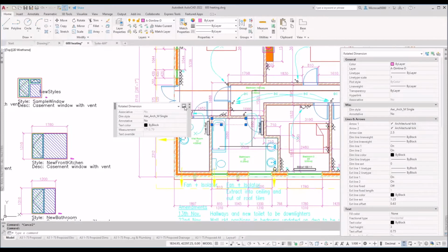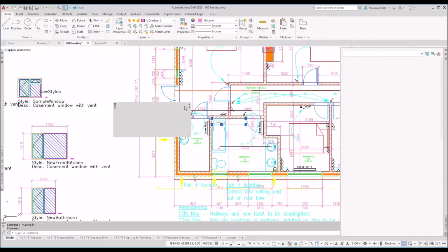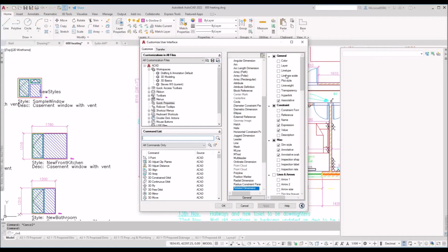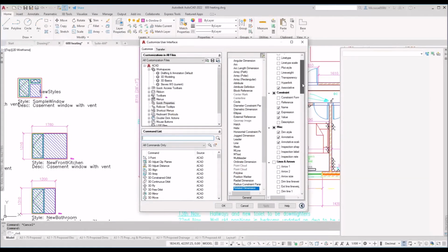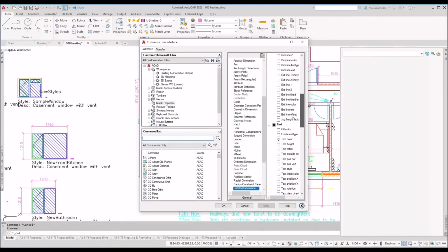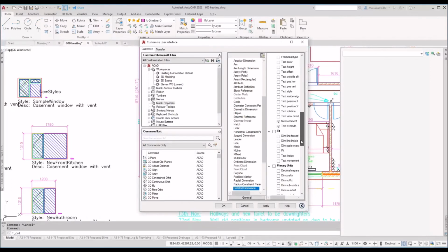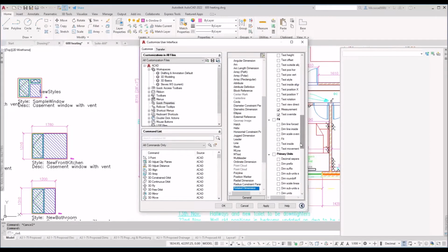If I click on where it says CUI, it goes into the customize user interface dialog box, and you can turn on and off in there the different options. So down here, look, you can set what the fill color is, or the text color. You can turn these things on and off, or your position. You can trim it down so it doesn't show. So I have to turn my suffix on. If I apply on that and OK on that.